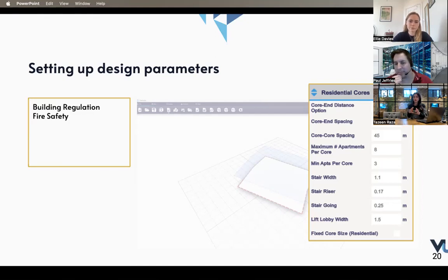As with any software, whether that's SiteSolve or any other generative design tool, one of the most important things is staying up to date with policy and how building regulations are changing to improve our safety over time. Quite recently, over the past couple of months, there's been a new legislation for the second means of escape staircase when a building hits a certain height. Once that was legislated, a lot of architects had to revisit a lot of their plans. And that's where Ramboll was instrumental in updating the code very, very quickly to introduce that functionality as well. So SiteSolve does take that into consideration for taller buildings.